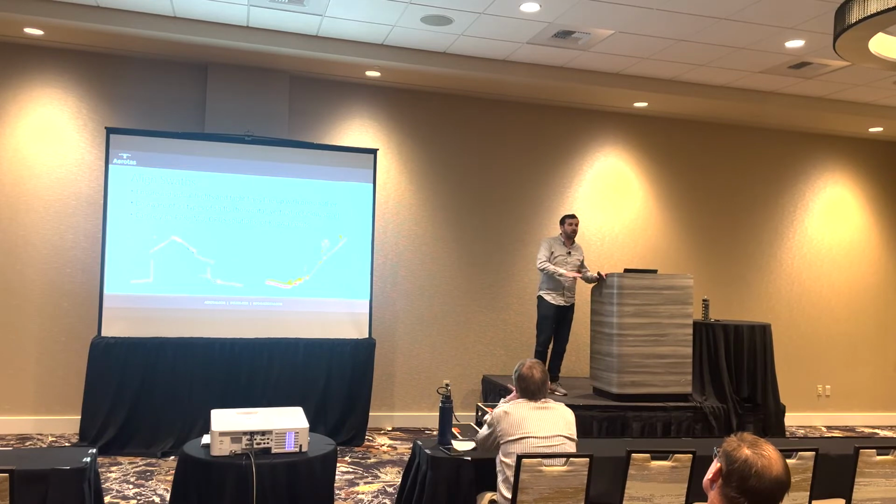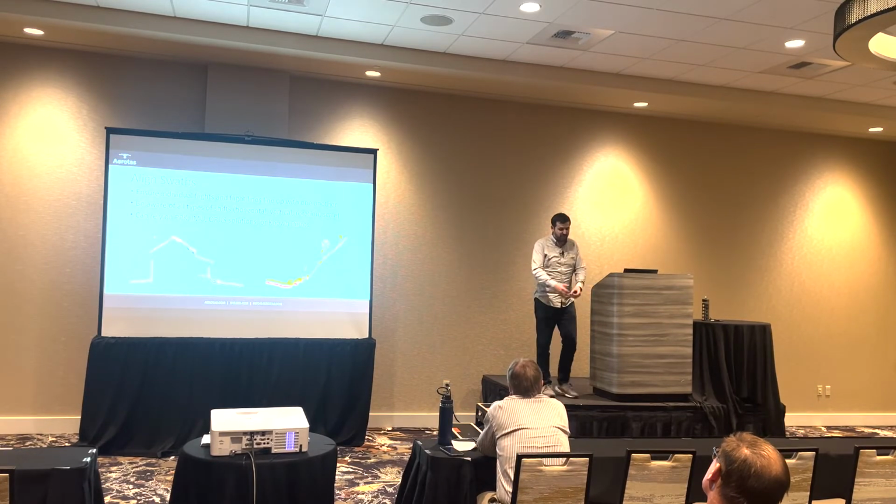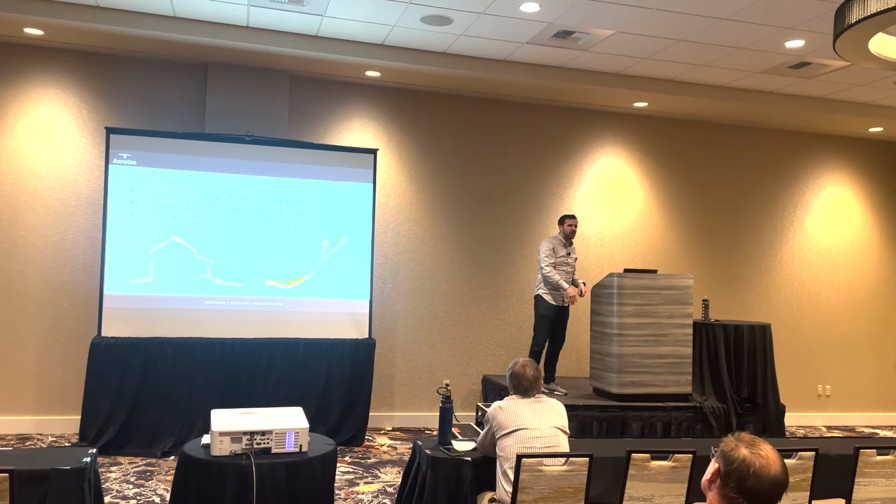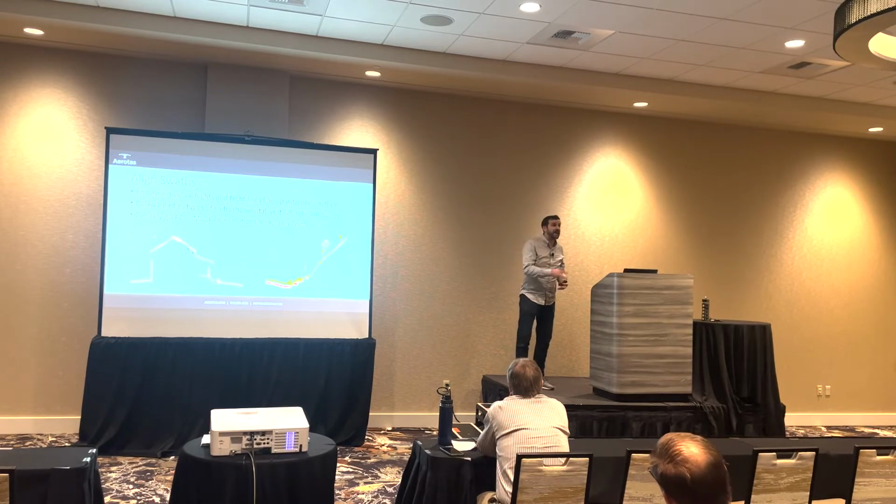It doesn't even need to be marked. We joke sometimes, you can even just take your GPS and just stab it into the ground, and as long as it's consistent, we'll just do an OPUS there and we'll make it work. Because that's a much more robust solution, and that can be done either with a Trimble or a DJI base station. We try and be very robust with that.